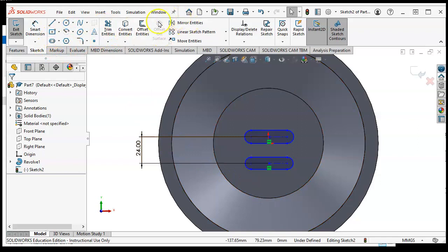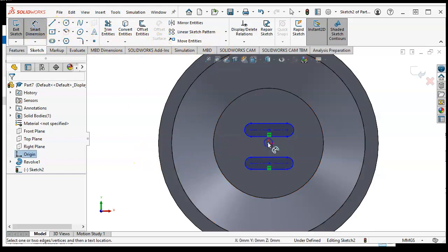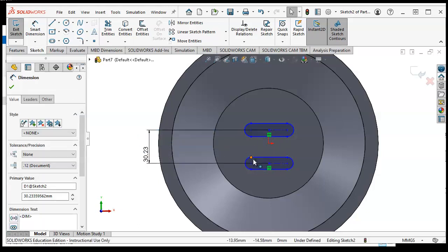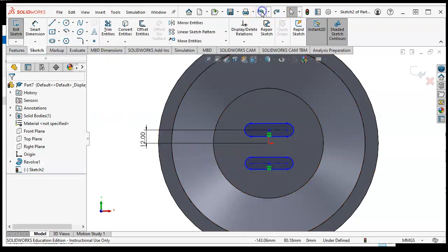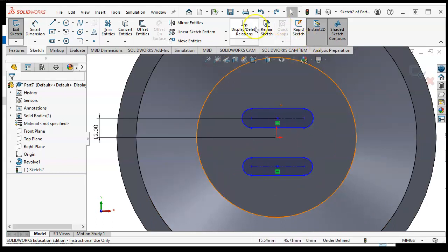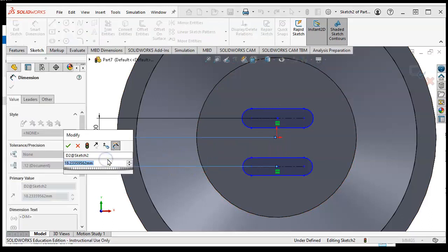Some mistake there. I'm going to undo this and see what happened. Probably I will erase this dimension and redimension this one. Something happened in the process. Pick the center to origin, 12, that's correct. And another center to origin. This would probably be the safest way to do it. Oh, again, something is happening there. Repeated the same thing. Okay, we have origin to center, and I'm going to do another one. Probably I should have gotten out of the dimension and repeated this. Now it's correct, 12.